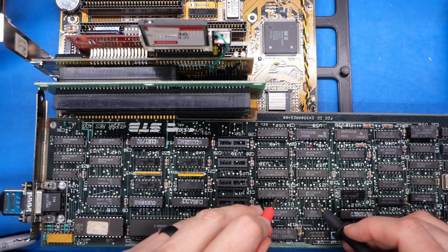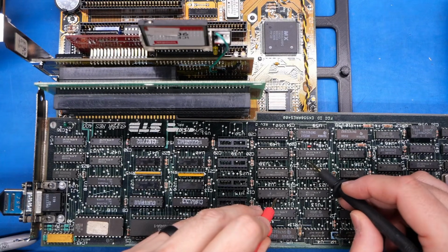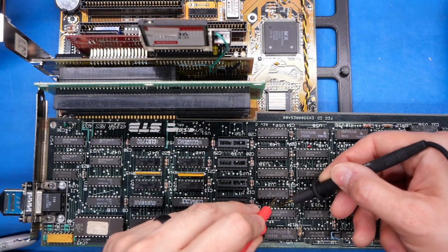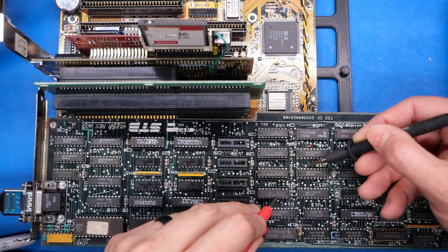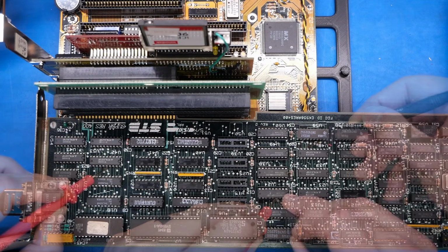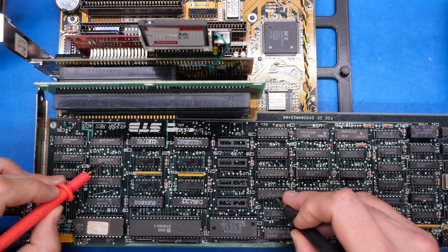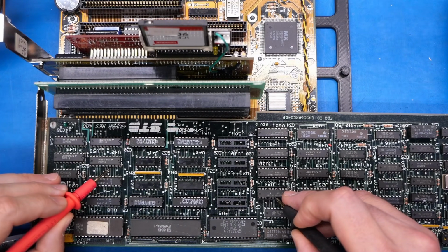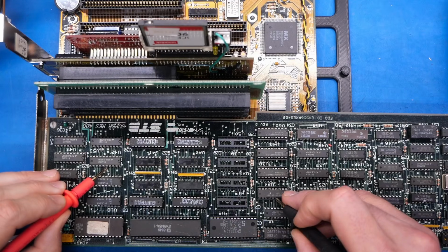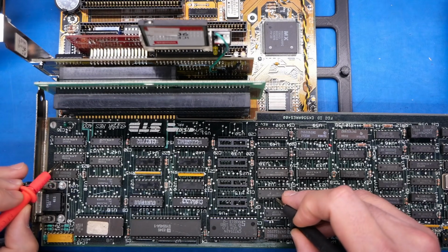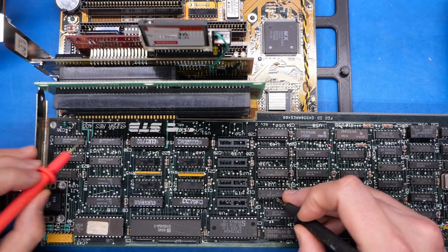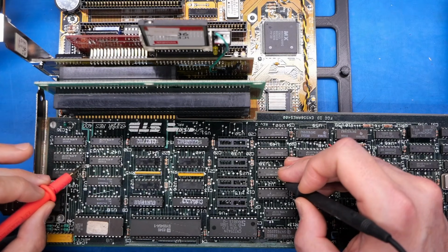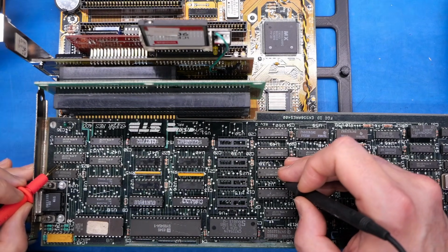Multimeter's ready. Let's just go over these chips here and see if any of these are connected to that pin. So far, nothing. Okay, so we have a connection over here. It's a 373, which I'm pretty sure is also a flip-flop. There's another connection right there. Same pin. No, different pin. So that's another 373. So it could well be these chips over here. So there's 4 of them there. So let's try pin 15 on the next chip here and see if it's over here. Yep, there it is on that one. There it is on that one as well.